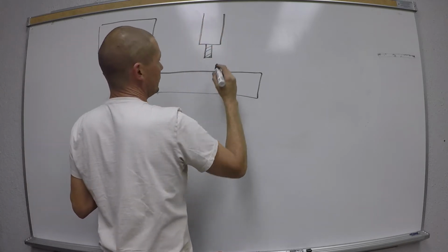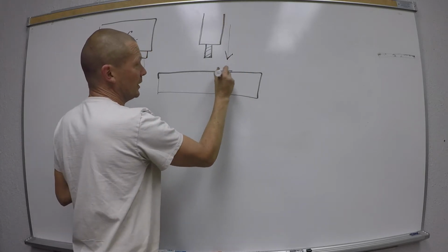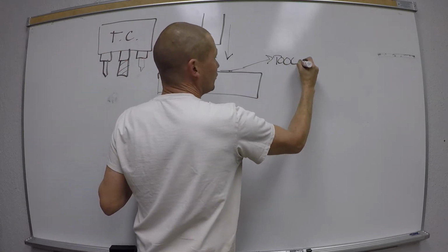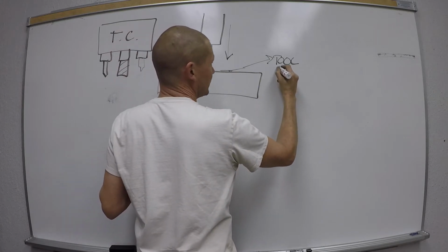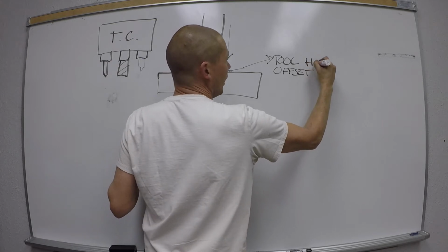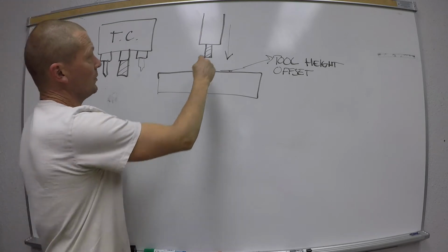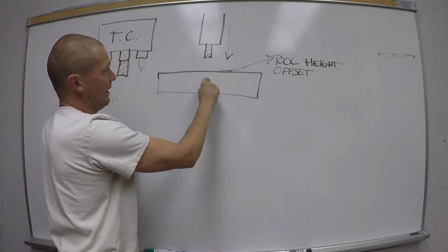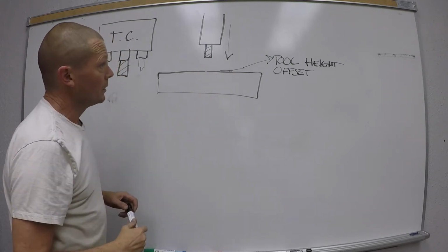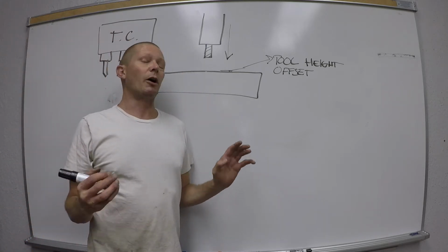What we do is lower the spindle really slowly, using the piece of paper trick, and give it a tool offset, more specifically a tool height offset. If I wanted this end mill to cut only about a 1/2 inch deep, it needs to know where the top of this is. So these are all things we need to do before we even start our program.